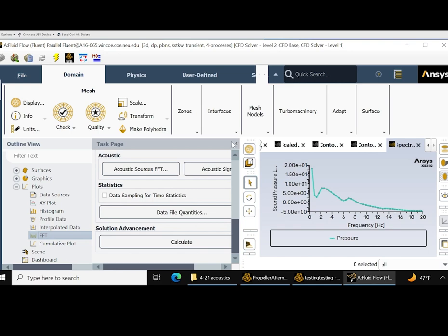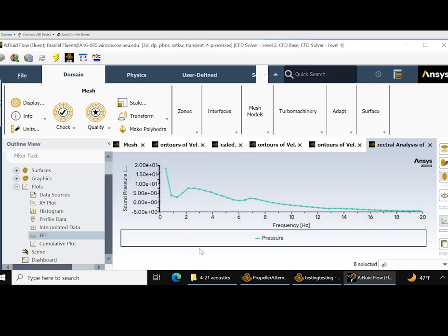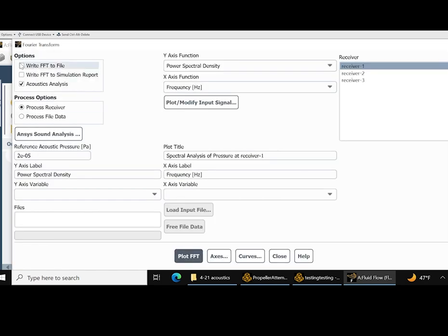And so here is the graph of the sound pressure level against the frequency. What this basically is, is that sound pressure level is in decibels, and at each particular frequency, it'll say the decibel of this frequency is a certain amount, and you can combine those values to get the overall sound pressure level, which is, if you have a device that measures the decibels in the area, the number you will see on the screen. We can also write this information to a file and process it in software like MATLAB or compare it against other plots, and so you can do that.